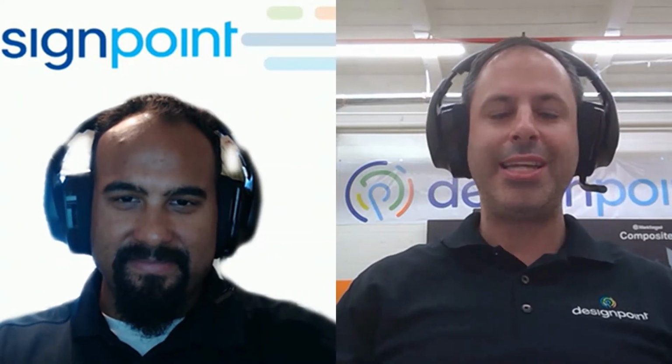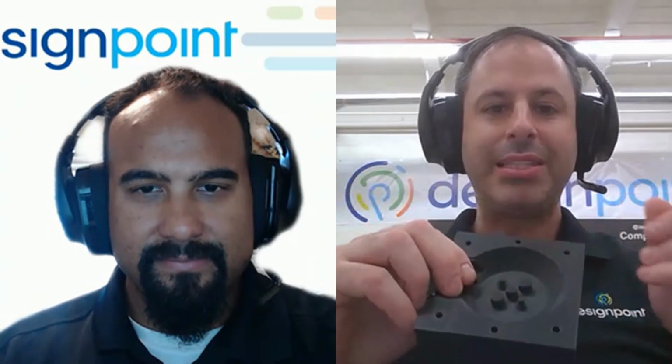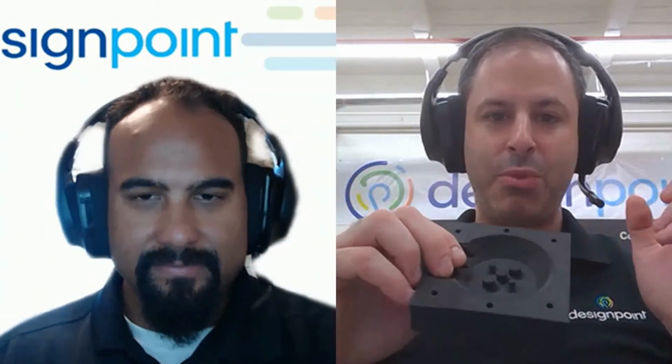And then there's another fiber, which I didn't mention yet, which is HSHT, high strength, high temperature fiberglass. This is a thermoset mold, which is printed in that carbon-filled nylon. But then we add high temperature, high strength fiberglass to this part. It does two things. One, it raises the heat deflection temperature, so you actually get a more resistant mold. I forgot to mention that before, that's another really good quality of this Onyx. It's 145 degrees Celsius heat deflection temperature, and it goes up when you add the fiberglass.